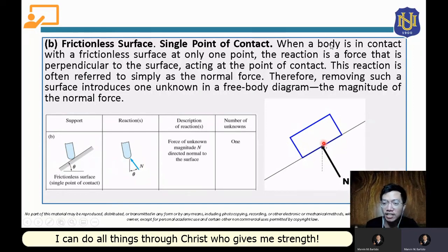Here the reaction force, or the normal force, will actually be a pressure, so it will be like a rectangular load. But as we have discussed in parallel force systems, we can solve for the equivalent point load of a rectangular load.